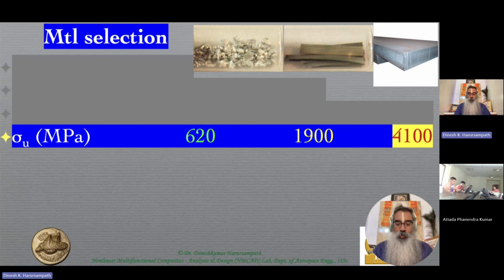So from this perspective, it's very clear that steel is a winner by a very big margin. If this were all the criteria used to select a material for a particular component, let's say the landing gear, then obviously steel is a clear winner. But that's one of the very few areas which still remains the realm of steel, whereas in most places, if not composites, it has been replaced by either aluminum alloys or titanium alloys.